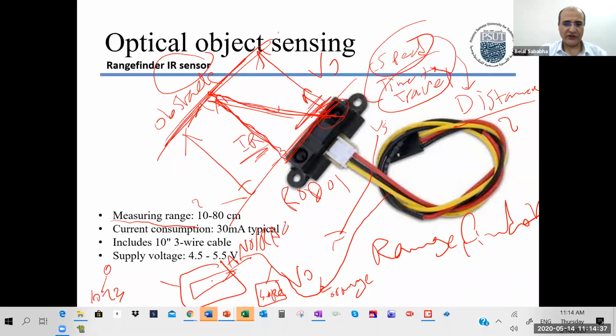Then you can read it into your A to D and get a number. If the voltage was small when you were very close and got larger when you got away, or vice versa, then the number will reflect this, because the number is the voltage, right? And the 1023 is 5 volts, the 0 is 0 volts, and everything in between is proportional.